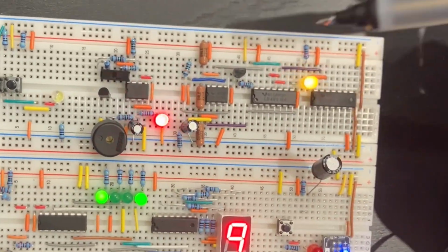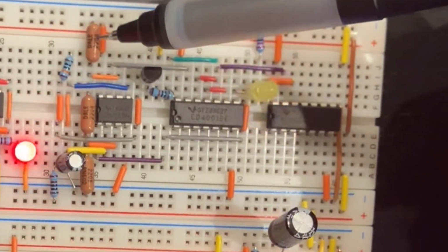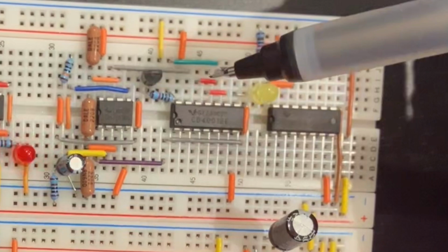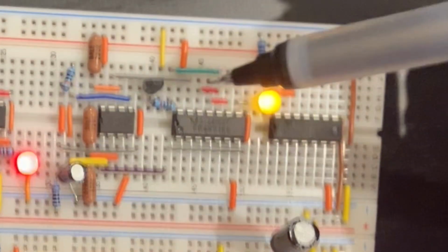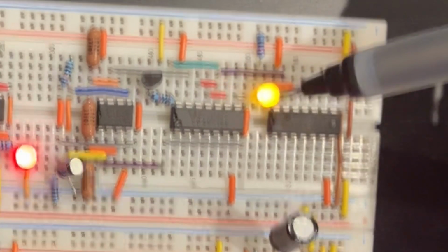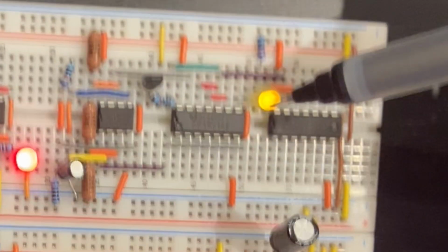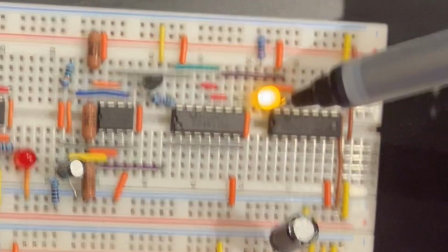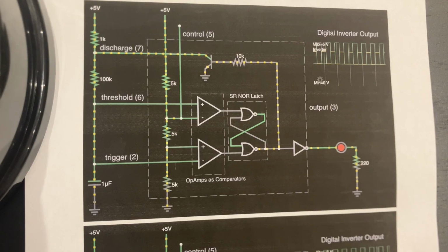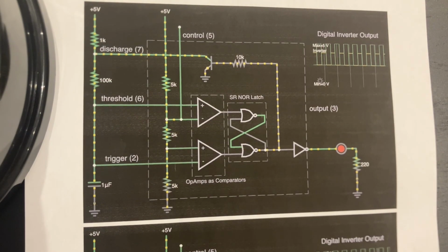This is the unpacked 555 oscillator, which shows the internal components of the 555 chip. It features 3 resistors of equal value that divide the voltage, 2 LM358 op amps used as comparators, a 4001 NOR gate used to make an SR latch, an NPN 3904 discharge transistor, and a 4069 NOT gate to invert the output. This is a Falstad diagram of the 555 unpacked oscillator.